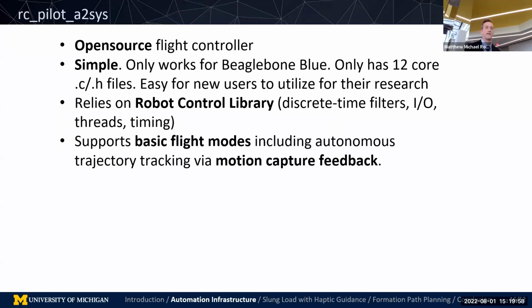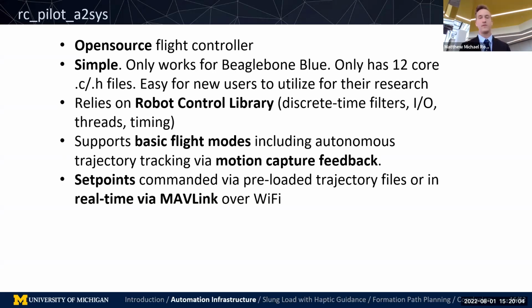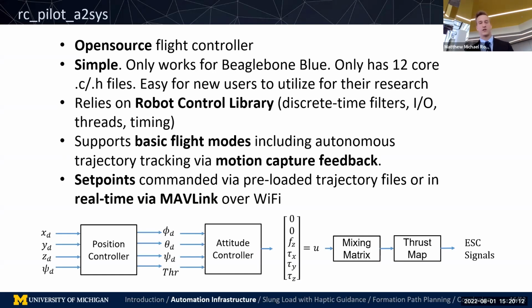And it supports the basic flight modes necessary to do the research. So this includes autonomous trajectory tracking via motion capture feedback. Setpoints can be commanded either a priori via trajectory files or in real time with Navlink over Wi-Fi. And so here's just an example to show from the very input to the output. So we have complete control over every aspect of this. We can log every signal and change everything that we want.